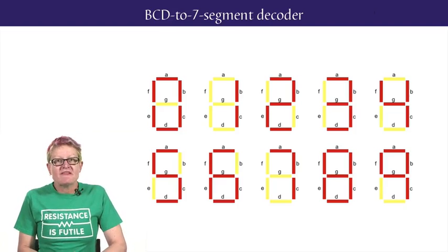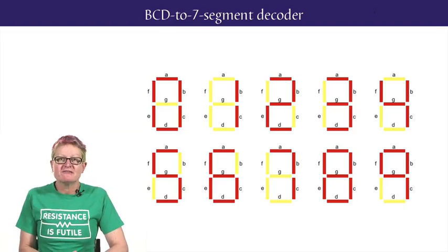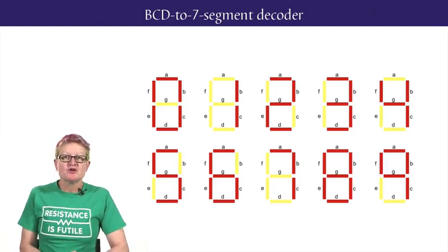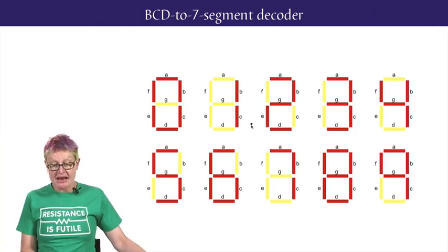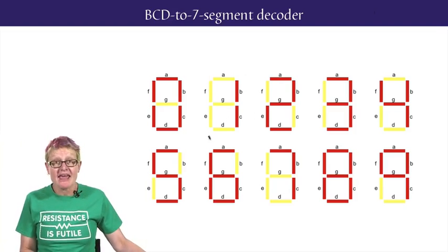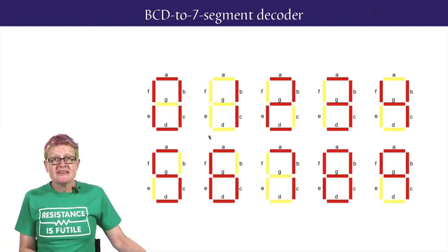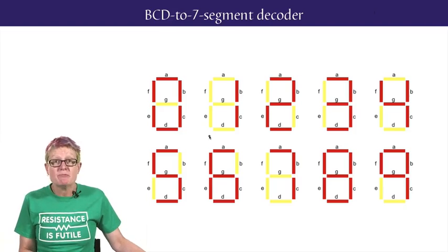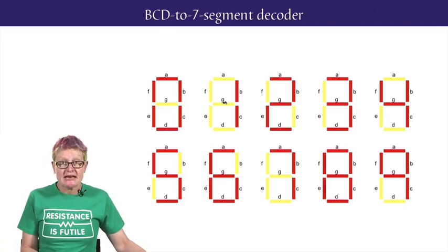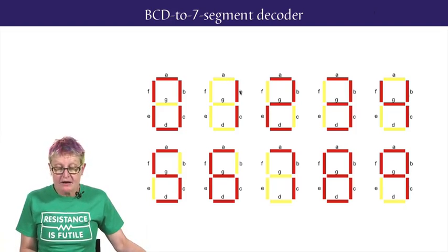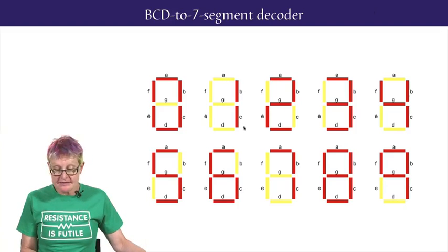Notice also that we have to agree on the pattern for the number 1, choosing to align it to the right of the display rather than, say, the left. The 7 segments are labelled A, B, C, D, E, F and G. The 2 segments needed to be lit up for symbol 1 are B and C.